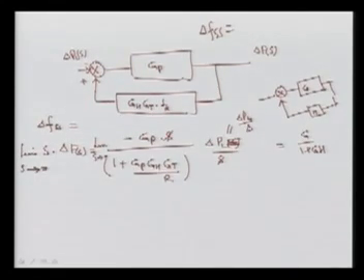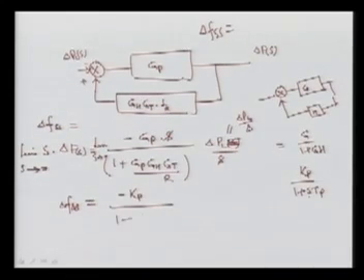Now you can see you have to put in the actual value. So here I can say the change in steady state frequency will be, first take this one, the GP. GP is nothing but KP over 1 plus STP. So if you put S as 0, you get here KP. So we are getting KP with a negative sign divided by 1, of course.